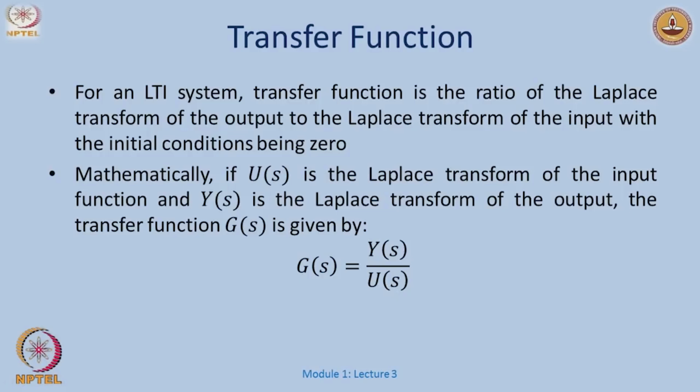So, how does this look? I have an input u(t) and an output y(t), and some system sitting here, which is represented by, say, an ordinary differential equation. I transform it into the Laplace domain, I have Y(s), and the linear relation which describes how a certain input results in a certain output is called the transfer function.